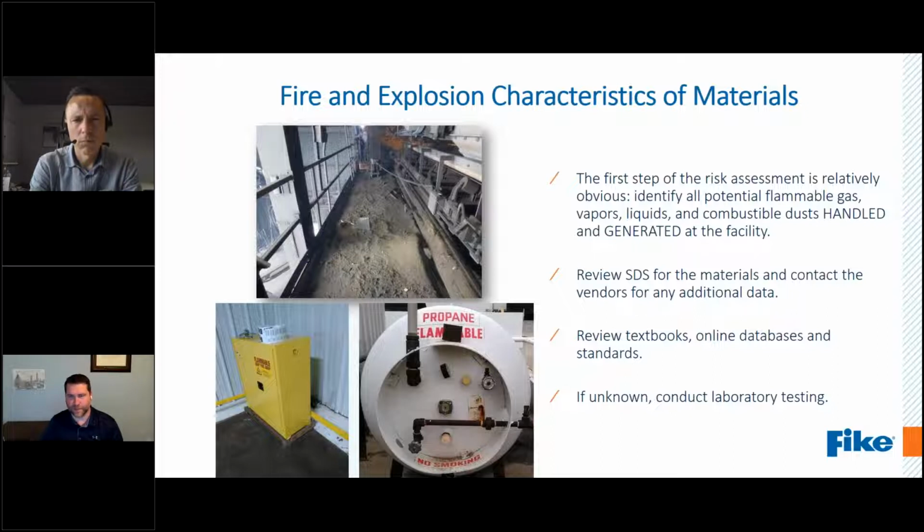I'm sure there can be a fire hazard. If there's a fire in the area, you've got combustible materials, but it's not really at risk of an explosion in storage. Whereas gases and liquids absolutely can be an explosion hazard in storage if there were to be a fire. So you do need to consider storage as well, even if it's bulk storage or you're just warehousing some flammable liquids for another facility.